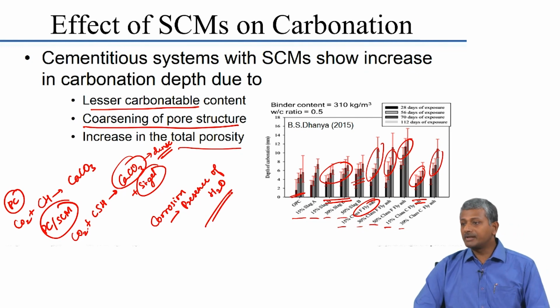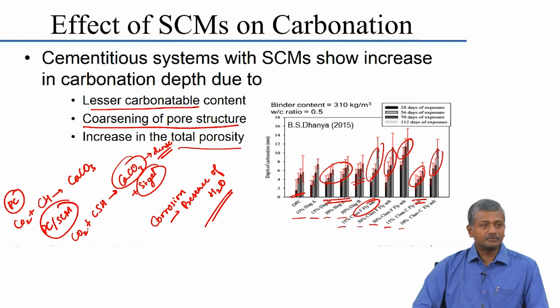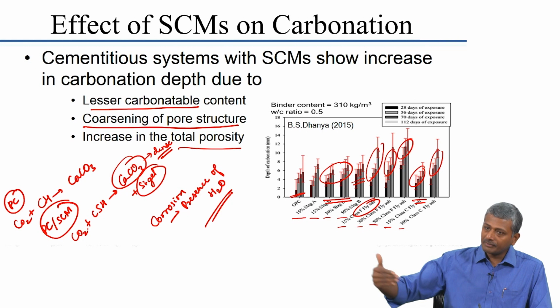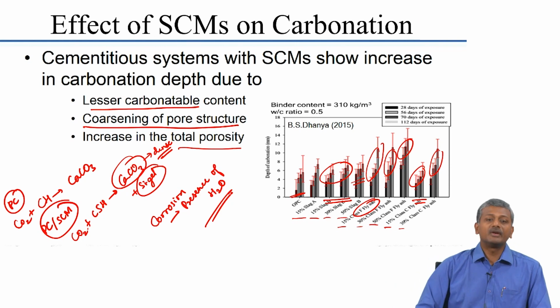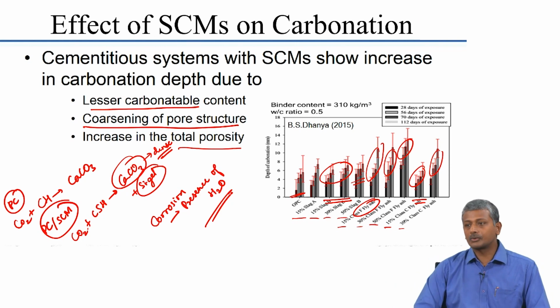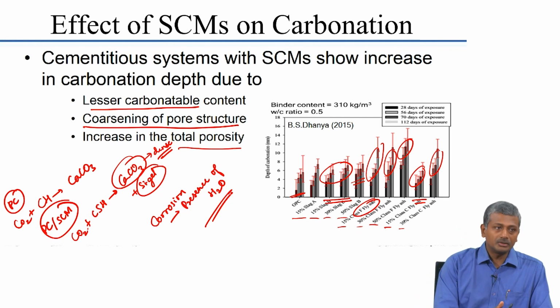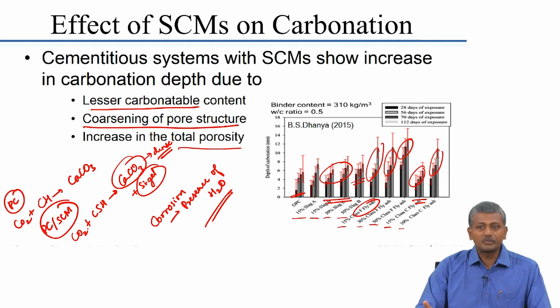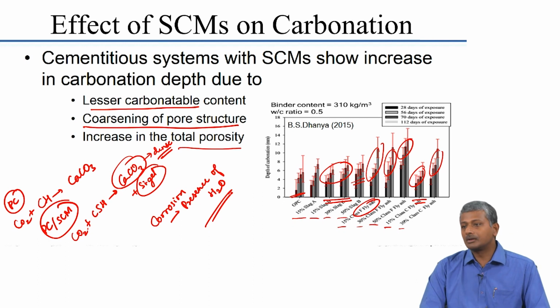And we know that in concretes that are saturated, carbonation is not really a big issue. Okay. So, when you have drying and wetting environments, that is where you will have the issue: in the drying environment you will have CO2 penetration, in the wetting environment you will have the access to corrosion. So, it is not that simple to convert this rate of carbonation to the rate of corrosion. It has to be understood with the help of experimental investigations whether carbonated concrete, when it is prepared with different types of binders, will lead to the same or different levels of corrosion of reinforcing steel.